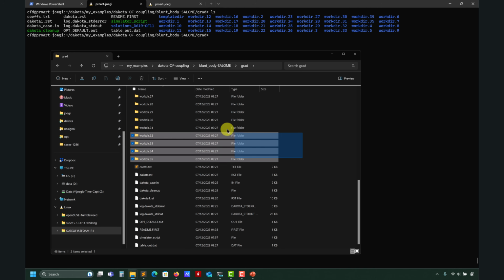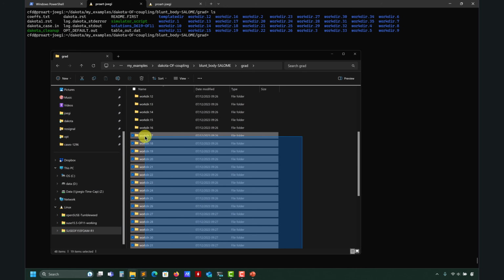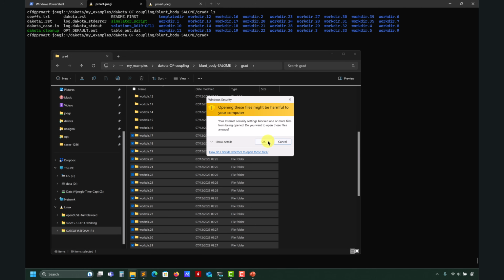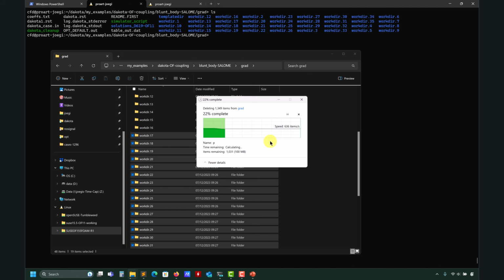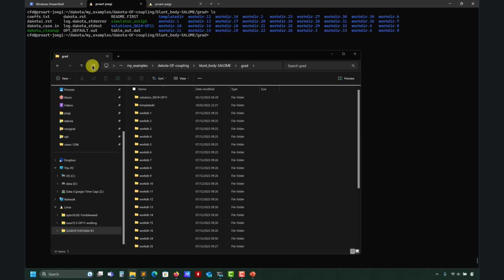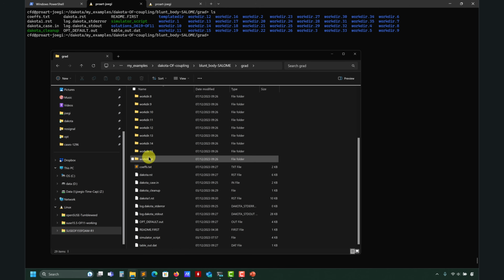So imagine that I was running this case and the case crashed at 16 iterations. Let me erase those iterations manually. Okay, I erase everything. So you don't need to restart from scratch. You can restart from 16. Usually the standard practice, at least for me, is to restart from 15 or 14, because this information might be corrupted.